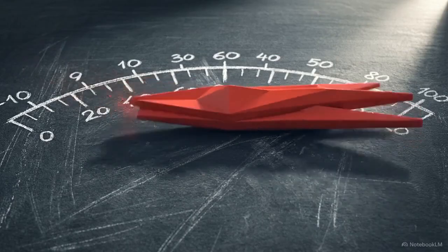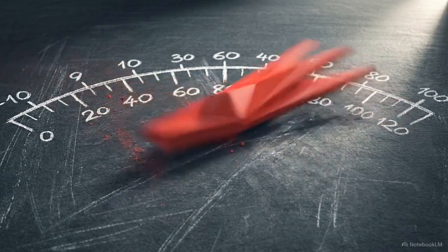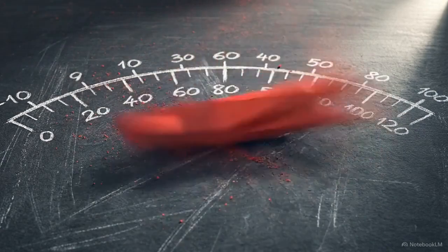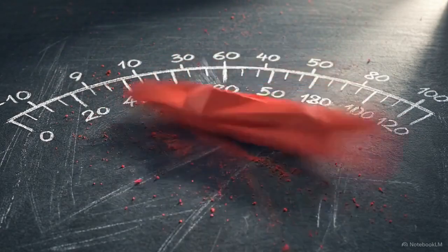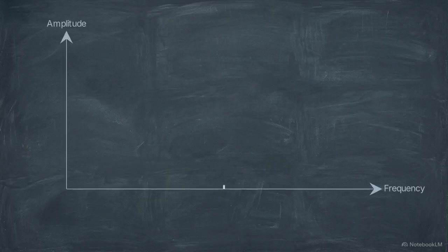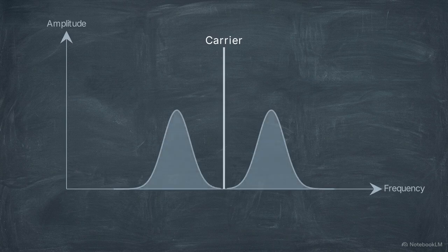This entire process demands exact precision. Without a perfectly phase-locked local carrier, the sidebands will fail to realign at 0, destroying the signal completely. Because homodyne receivers need precise synchronization, they're expensive to mass produce. Standard amplitude modulation became the historical workaround. Standard AM transmits a massive, continuous carrier spike alongside the sidebands. This allows receivers to rely on cheap, simple envelope detectors to read the signal.